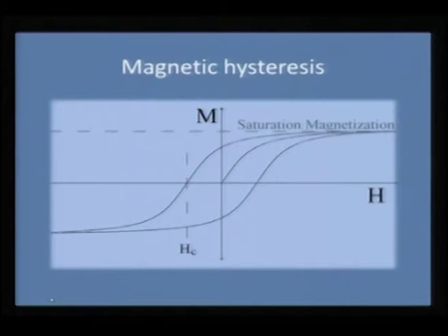A typical magnetic material would give a hysteresis, where two parameters are very interesting to follow. One is saturation magnetization. It is when you take the virgin sample and increase the field, then it gets saturated, and on removal of the field, it will not take the same path as that of the MS, rather it would keep going down, where this is your MR, that is the remnant magnetization. To completely revert it to 0 magnetic moment, you need a field which is called Hc, in other words the critical field or coercivity, and that coercive field is the strength of how much the magnetic moment is aligned.